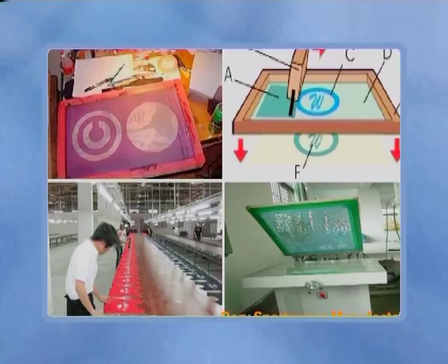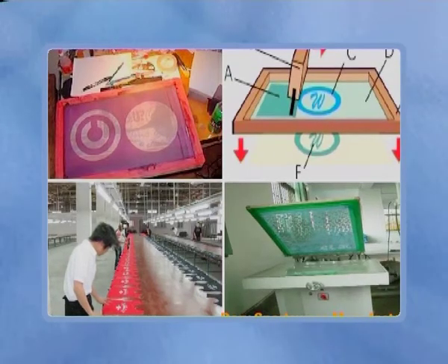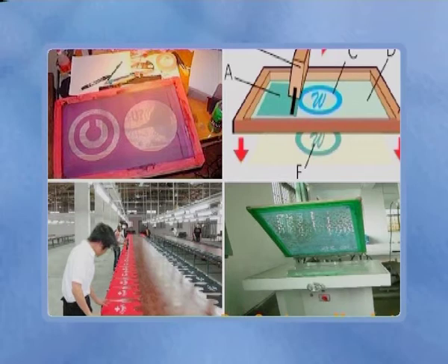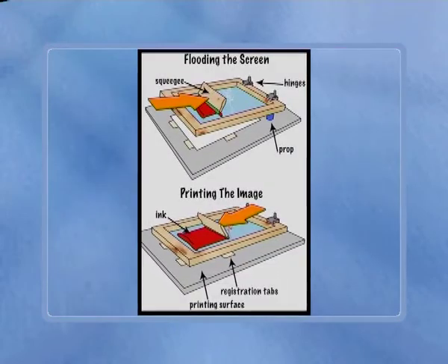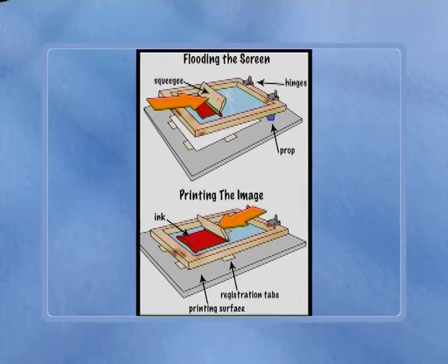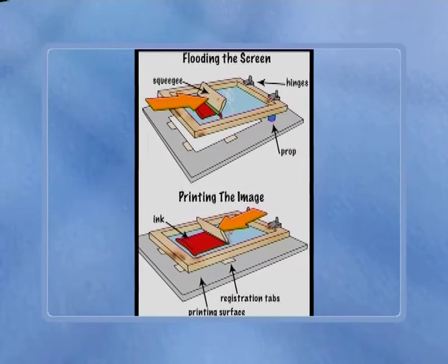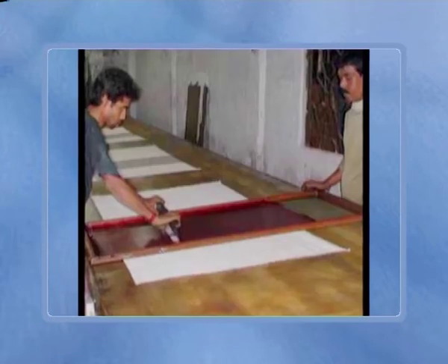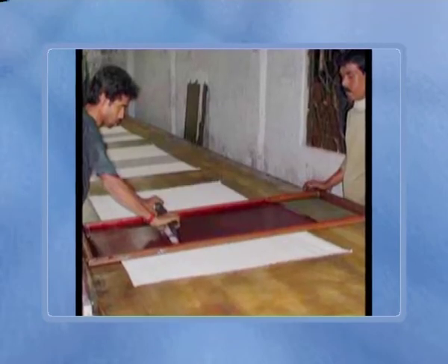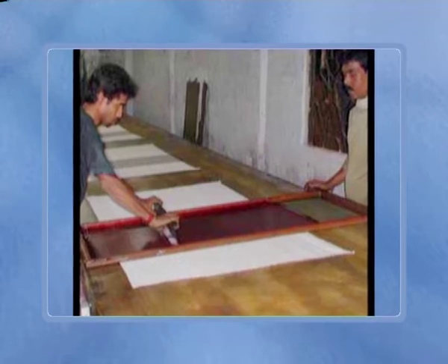Screen printing is one of the cheapest printing processes and can be done fairly easily. It is a printing technique that uses a woven mesh to support an ink blocking stencil. The attached stencil forms open areas of mesh that transfer ink or other printable materials, which can be pressed through the mesh as a sharp-edged image onto a substrate.